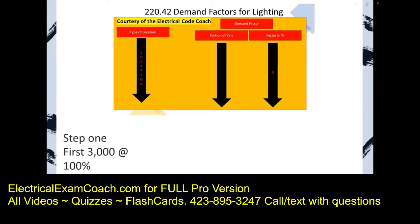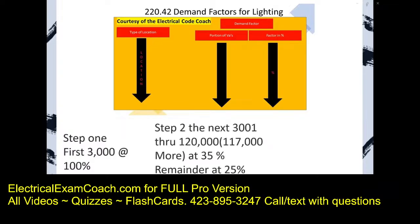Step 1, we're going to take the first 3,000 VAs at 100%. Step 2, we're going to take in between 3,001 through 120,000, which is technically just another 117,000 more. And that's how I'm going to refer to it for the rest of the program. We're going to take that percentage at 35%, and then we're going to take anything above and beyond that at 25%. Then step 3, we add them back together.